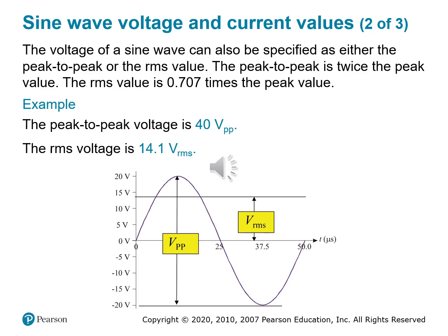This is useful when you're visualizing the entire range a waveform occupies on a scope or an input terminal. When we say RMS voltage, root mean squared voltage, this is a kind of average, but not a simple one. It tells you the equivalent DC voltage that would deliver the same amount of power.